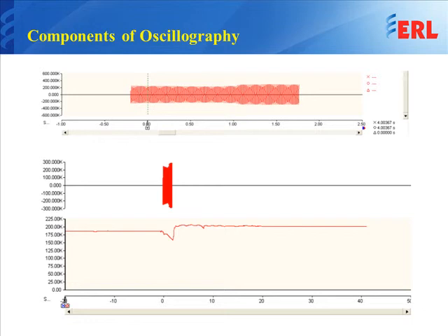So the swing record is the last trace there, and it has been shrunk to capture the entire event during 50 seconds. So we can see what the overall response of the power system is for this record. We can see that the voltage has dipped down there, and then you can use this record to analyze how generation would respond, and you can export this record and import it in a program such as PSSE.